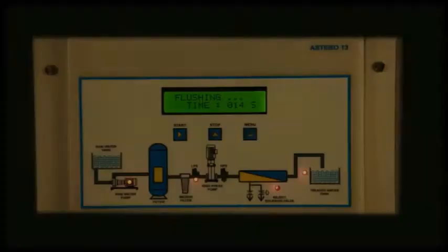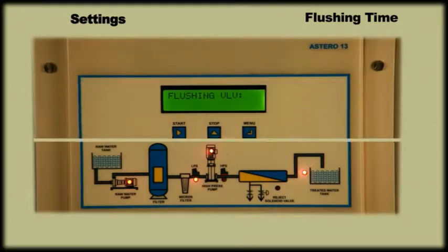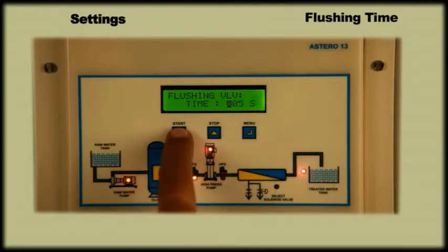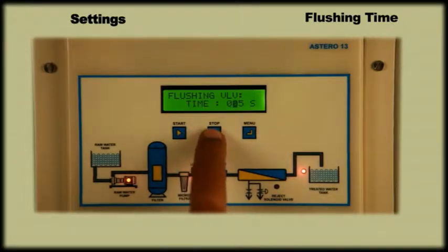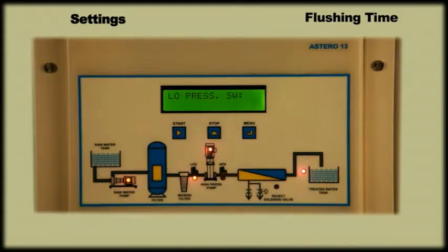Flushing time. The flushing valve remains open for the set time during the startup and shutdown. We recommend the flushing time should be set such that the TDS of reject water drops down to almost equal to the feed water during the starting and stopping sequence.